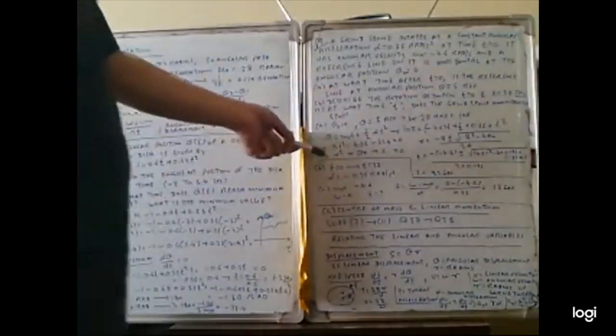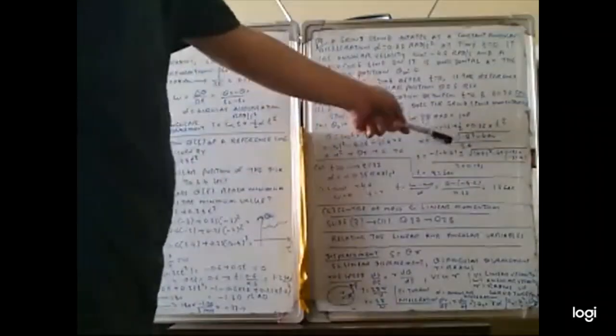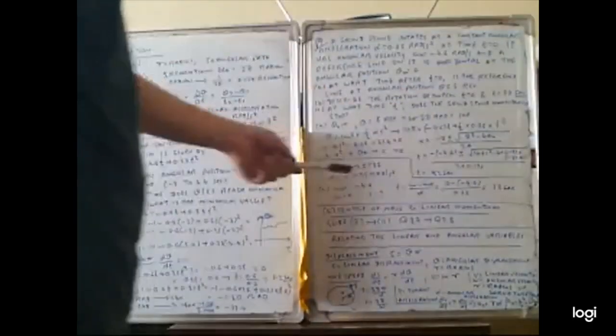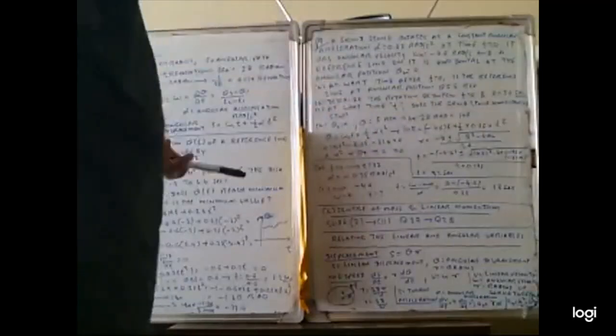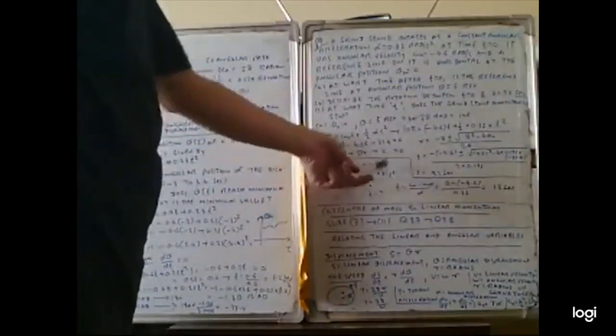So we compare with the formula A T squared plus B T plus C equal to 0. T is equal to minus B plus or minus square root of B squared minus 4AC, divided by 2A. So in place of B we can substitute minus 4.6, and also A is 0.175 and C is minus 31.4. So you substitute, and T is 32 seconds. Then from T equal to 0 to T equal to 32 seconds, alpha is 0.35 radian per second squared, so this is a rotation with deceleration.